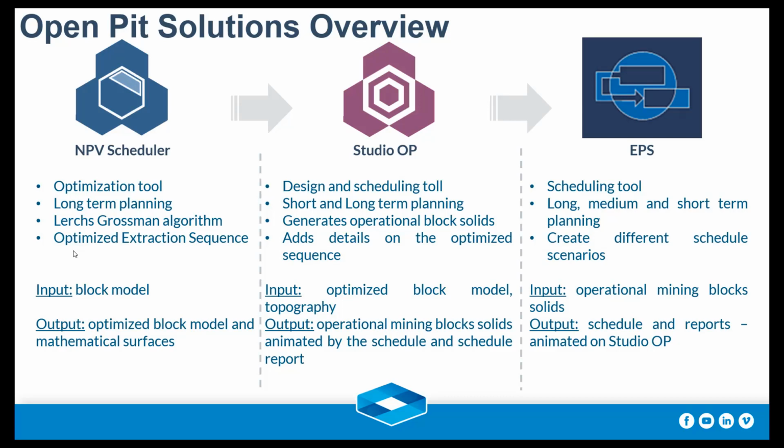Studio OP, on the other hand, is a design and scheduling tool. It doesn't have an optimization into it. So Studio OP works with short and long-term planning. It works with surfaces and DTMs, so you can load in your real topo, do your real pit design, and create your operational blocks.